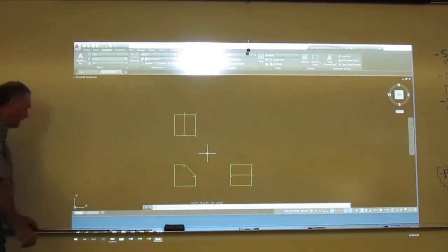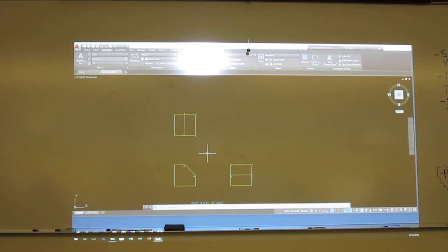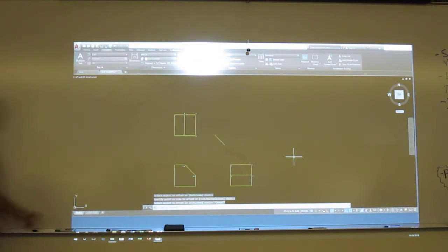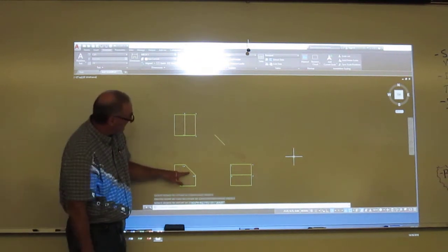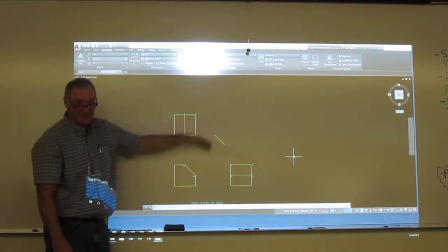Now it's really a fairly simple process. Usually the reference plane will reduce steps you need to do. So here I'm just going to do an offset of 6. I'm just going to throw that thing out. So I just did an offset, and I offset the edge view of my inclined plane out, and I just went 6.